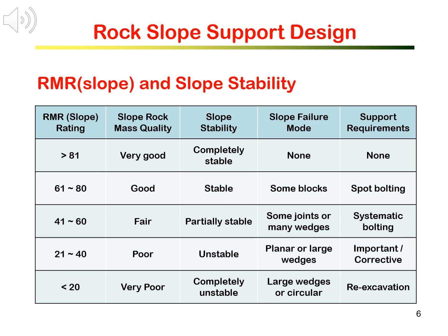For poor and very poor rock mass, much more extensive supports are needed, including concrete retaining walls and other heavy supports. Apart from using very heavy supports, re-excavation of the slopes, for example, to a gentler slope angle or to undulate the sliding planes, can also be considered.